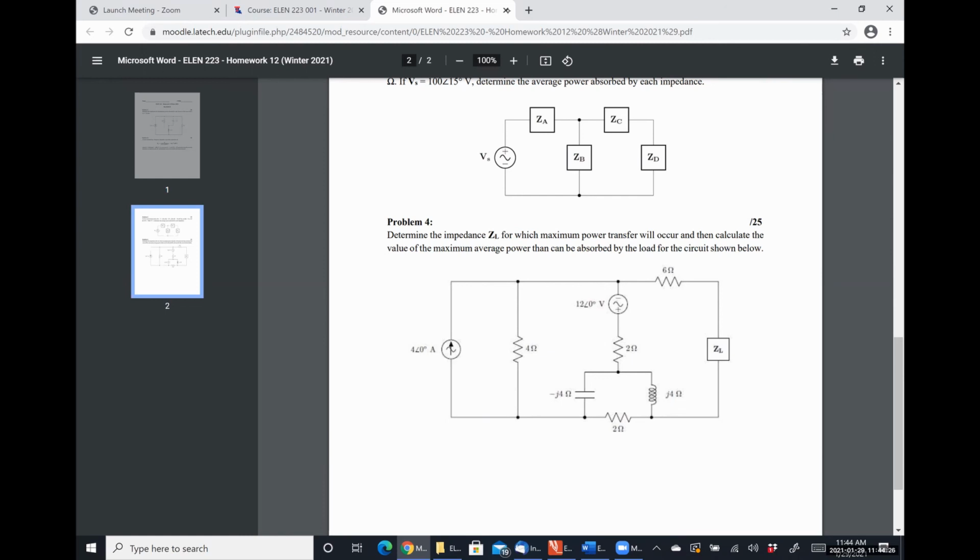Okay, so this would be what's considered a delta network. In order to do a resistor combination technique here, you would have to do what's called a delta to Y conversion, which I believe I made you do strictly with resistors way back on homework set number 1. Those exact same rules apply for impedances, so you could do that.